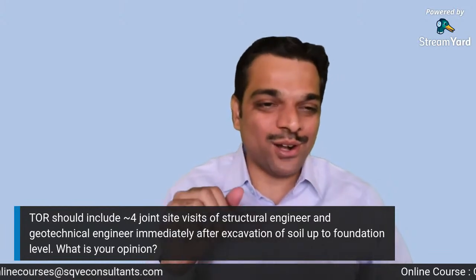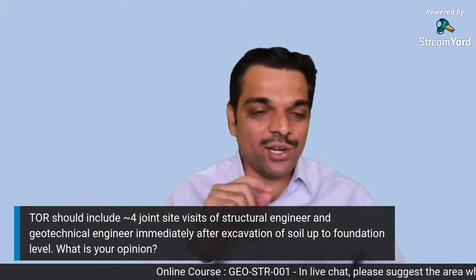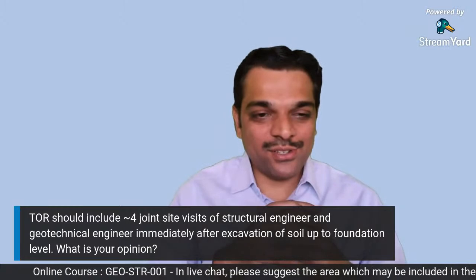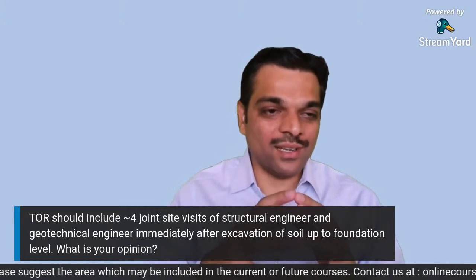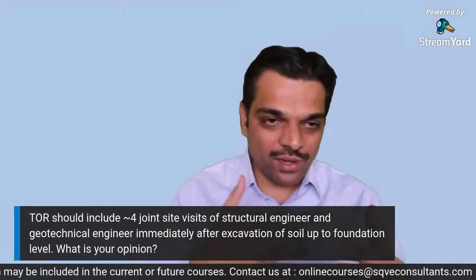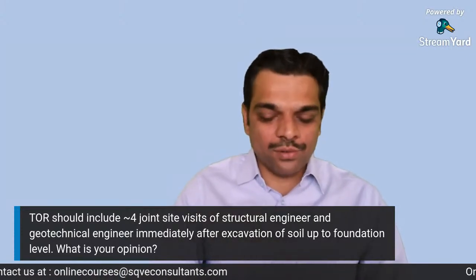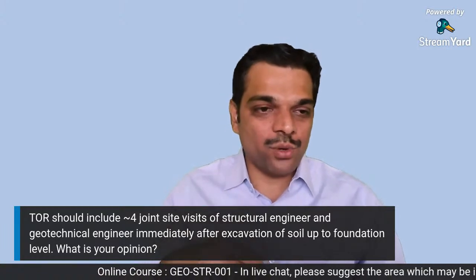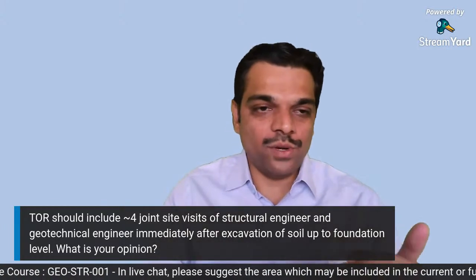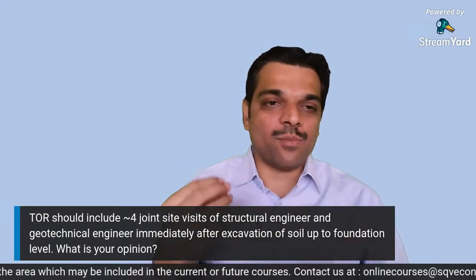Okay, this is what we were talking about: the TOR, terms of reference, should include at least 4 joint site visits of structural engineer and geotechnical engineer immediately after excavation of soil up to foundation level. What is your opinion? I think this is what we have discussed. I think it must be done. This is an excellent point. It must be included, so that the costing and the time is already counted by the geotechnical investigation agency, so that during execution you can do it immediately. But generally, I have seen that joint visits are not included as a part of the terms of reference.